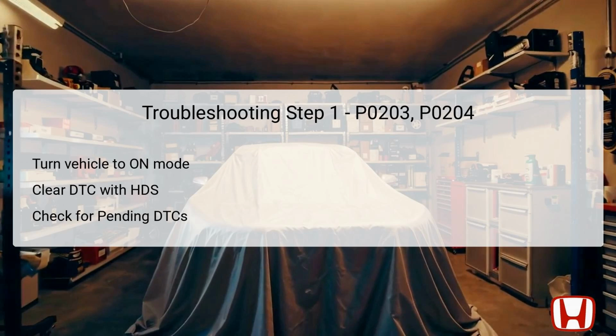After clearing, turn the vehicle to off mode, then start the engine. If the engine does not start immediately, crank it for at least 20 seconds to allow the system to initiate. Finally, check for any pending or confirmed DTCs with the HDS. This will help identify if the codes appear again and determine if the issue is persistent or intermittent.